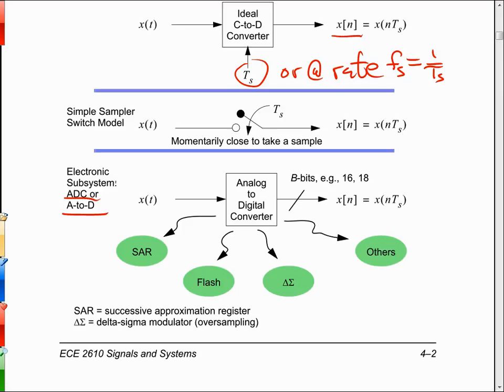Not aliasing, but fidelity. We have more error, so we have what's called quantization noise that creeps in the background. A 16-bit converter, it's not a subject of this class, but a 16-bit converter will give us a signal to quantization noise ratio of around 95 dB or so. Most of us can't hear that dynamic range all that well because 90 dB is a lot of dynamic range.